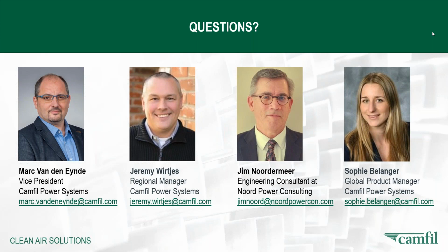Thank you. I have one question that's a little bit more specific here, but maybe we can take a more general approach to answering it. A customer is asking about a GT26 gas turbine with a 3-stage filter from a competitor, G4 M6, and a final E10 filter in 330 millimeter depth. He has a problem where the final filter life was only 6 months, and he's asking what could be various strategies to increase the life of the final filter. What is the first idea that comes to mind if you want to increase its life cycle?